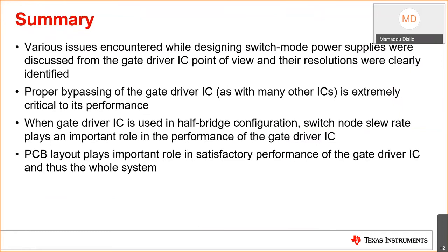Also, when using a gate driver in a half-bridge topology, you want to make sure that you're controlling the slew rate on your switch node, because the high side channel is referenced to that same switch node. So you want to make sure that you can control that with either a sufficient gate resistor accounted for, or making sure that your dV/dt is within the driver specifications.